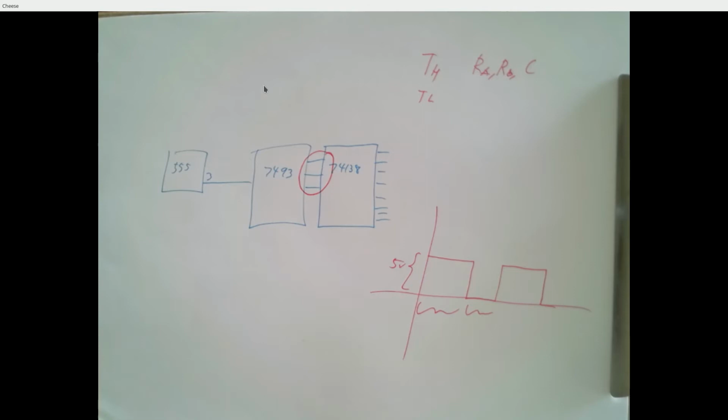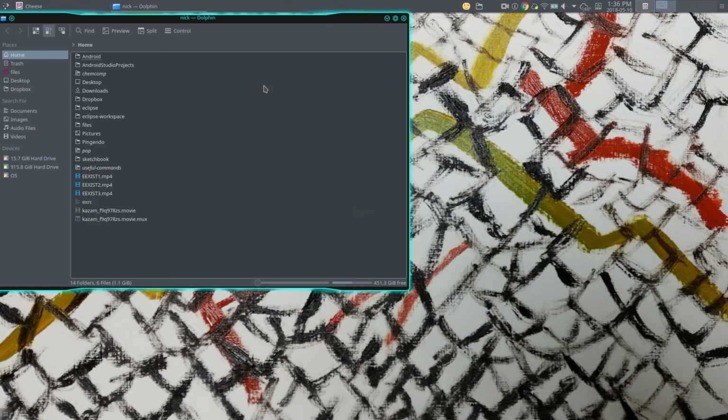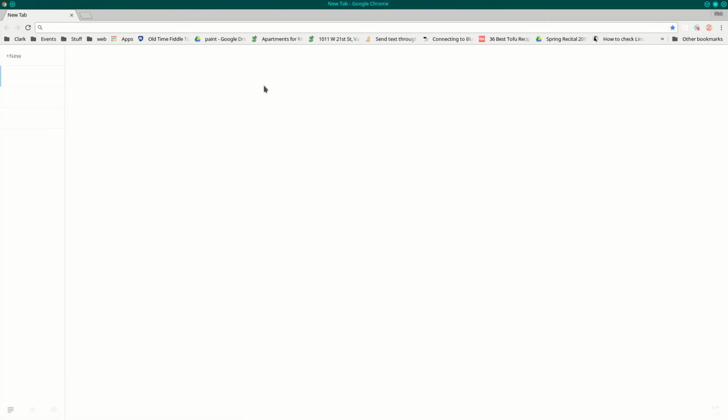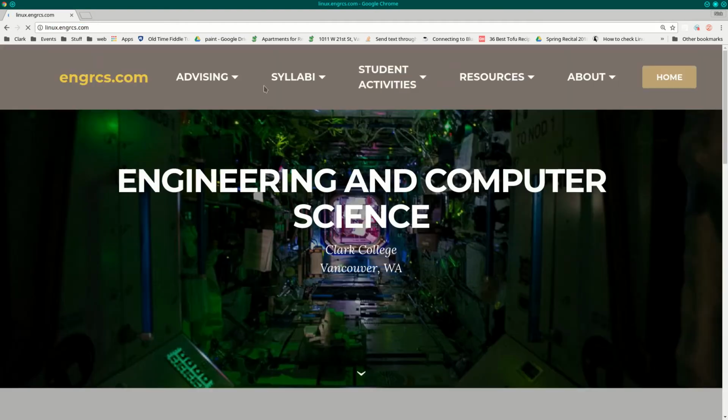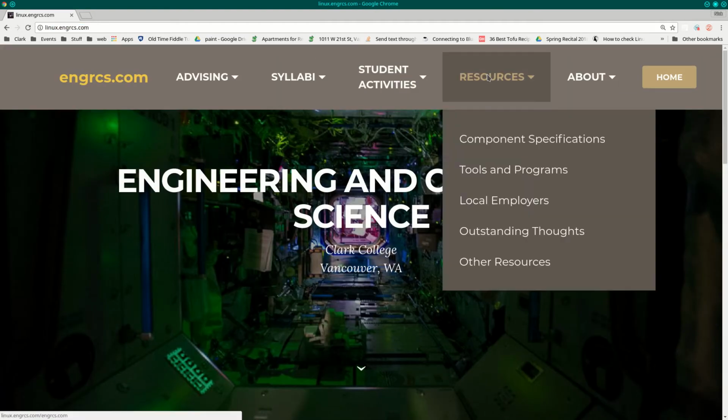Okay. I had a similar issue where one of the counter outputs was stuck on, and my resolution for it was adding a resistor in to the output from pin 3 of the 555. For some reason that allowed it to work properly.